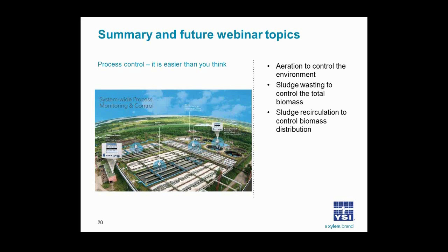Okay, thanks, Rob. Next question. Can nitrate measurement also be used for aeration control? That's another very good question, and it can be. Obviously, nitrate is a product of nitrification, so as ammonium goes down, nitrate goes up.